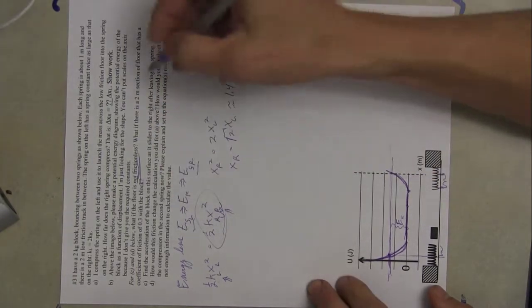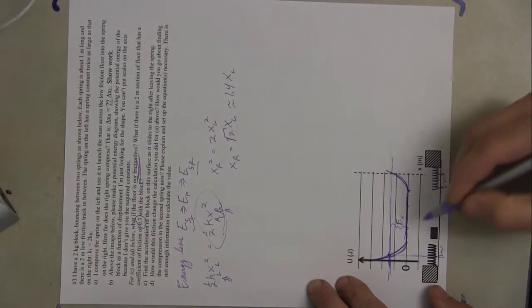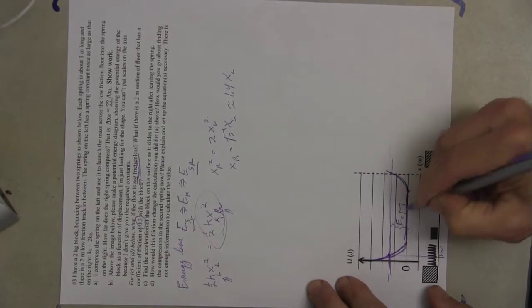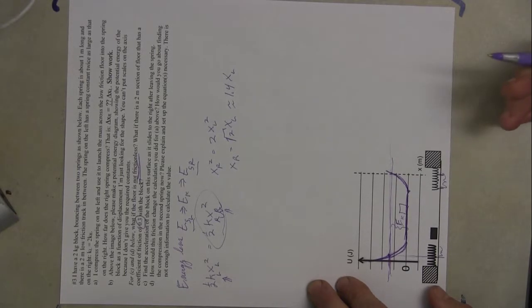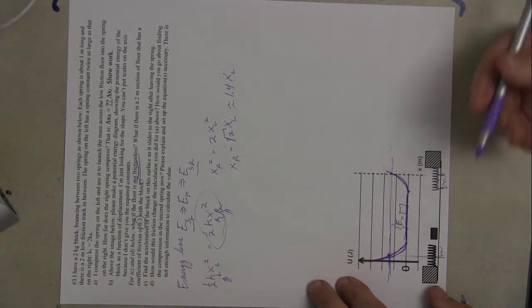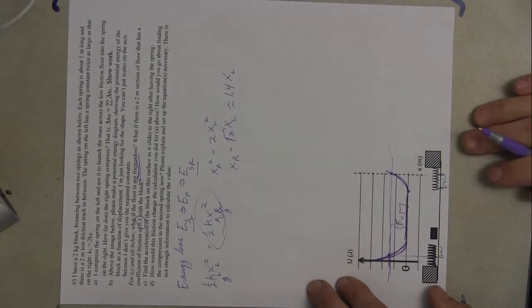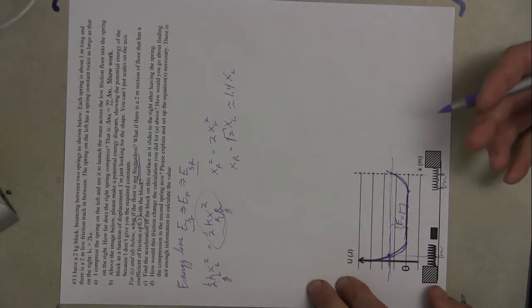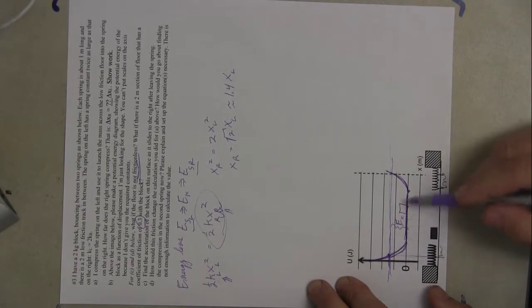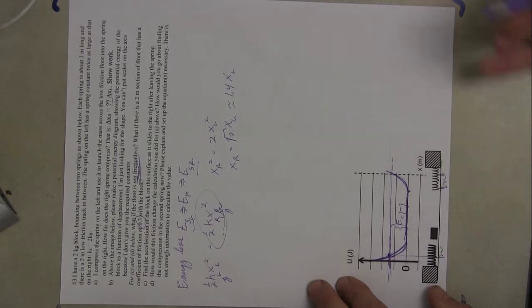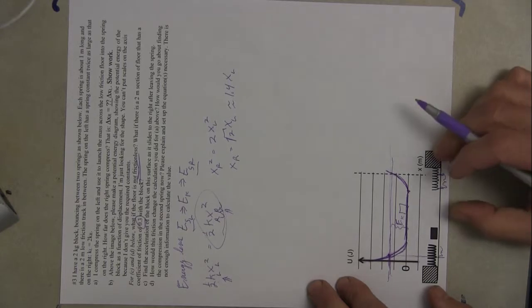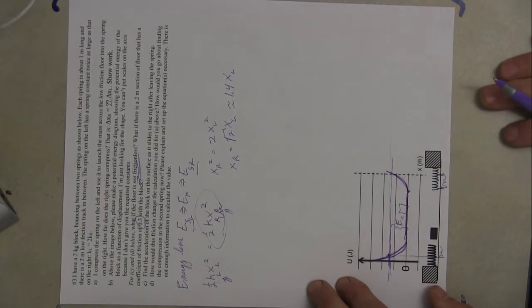What if we have friction and there's a coefficient of friction of 0.3? Then as this block slides along, there's going to be a frictional force. And we can look at this through two lenses. One is that friction will accelerate it in that direction. But two, that friction will also turn some of its kinetic energy, what was originally spring potential energy, into heat through the work of friction. So the final compression here is going to be less.